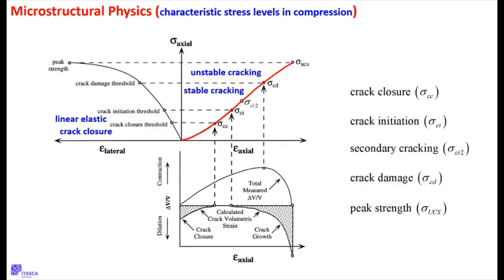And that's crazy. There's much more complicated stuff going on, and all of these processes are going on for any kind of rock. They're very pronounced and very clearly describable for a granite, and there are different mechanisms going on for a sandstone. What I'm trying to get at here is you can have many different rocks that have the same E and nu and UCS.